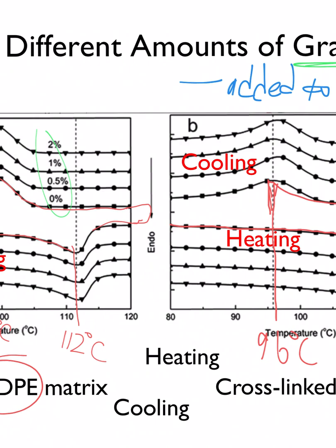All right. So crystallization still wants to occur at some point, but the crosslinks are getting in the way. So you have to suck out a little more energy to get them to finally line up and crystallize with each other. And it wouldn't be a huge shock if you got less crystallinity. Instead of, I don't know, 44%, it might drop down to 43% crystallinity when you have cross-linking present. You still get crystallinity, but you may slightly affect it. All right, does that make sense?